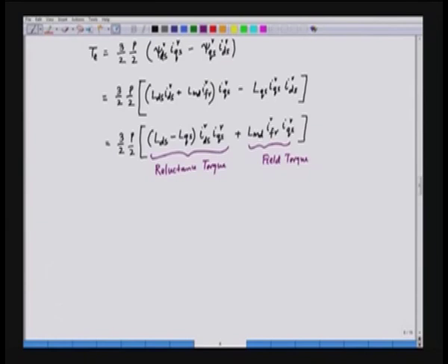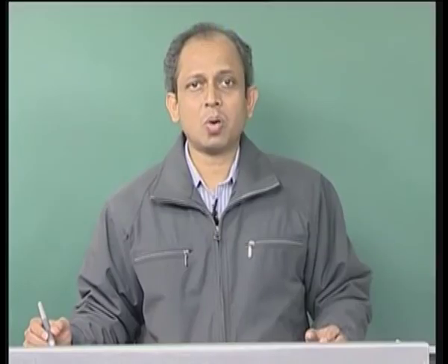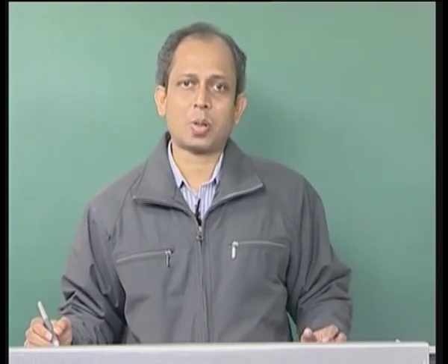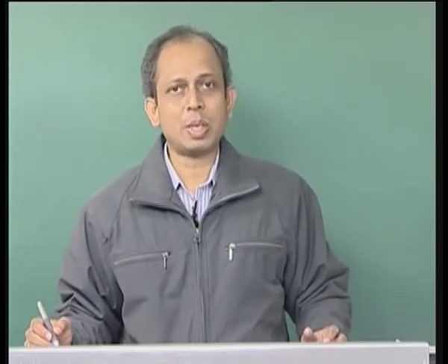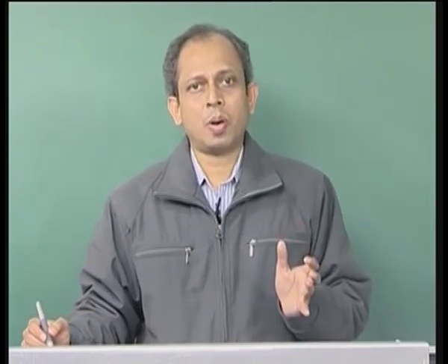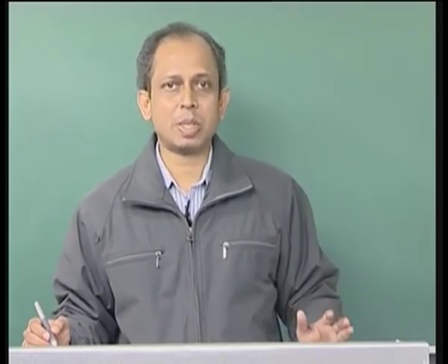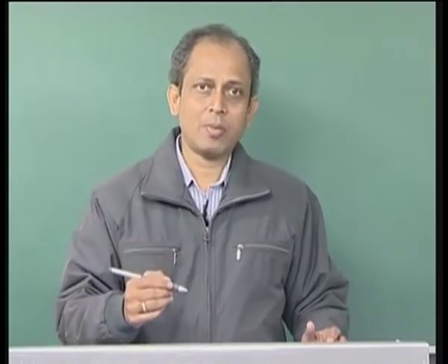Now, we will implement vector control. In vector control, what we do, we try to independently control the torque and the flux, just like a DC machine. So, vector control of a permanent magnet synchronous motor aims at control of the torque and flux independently, just like a DC machine. So, in this case we can just go back to our phasor diagram.